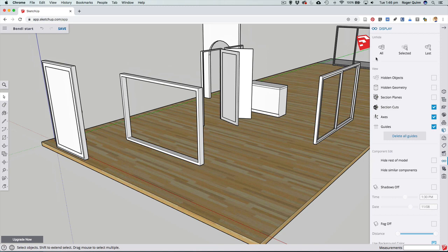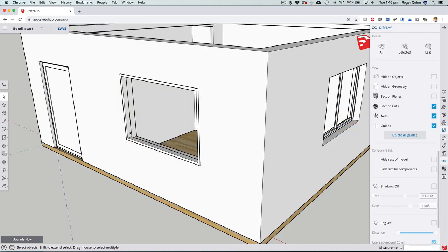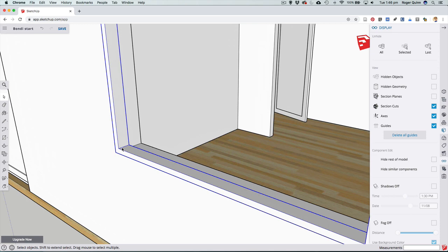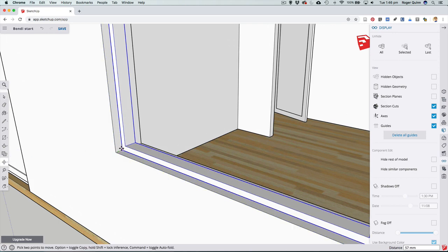Perhaps before I do that, I'll just bring back my walls by unhiding them. What I have been doing, just for consistency purposes, on these outer frames of the windows, is getting the Move tool and then insetting them a little bit inside the cavity. And I think I've used 60 on all the other ones.